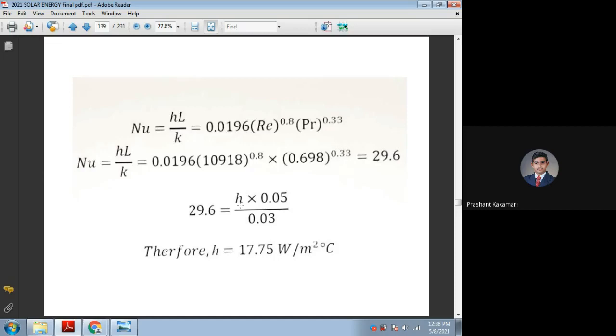So this h value may be used in this heat balance. What is that heat balance? In the performance we have seen, the heat balance is heat absorbed by the plate and heat gained by the air. That is the balance. So theoretically we always assume that whatever heat is transferred by the heat exchanger or the air heater, that heat will equally be absorbed by the fluid also.